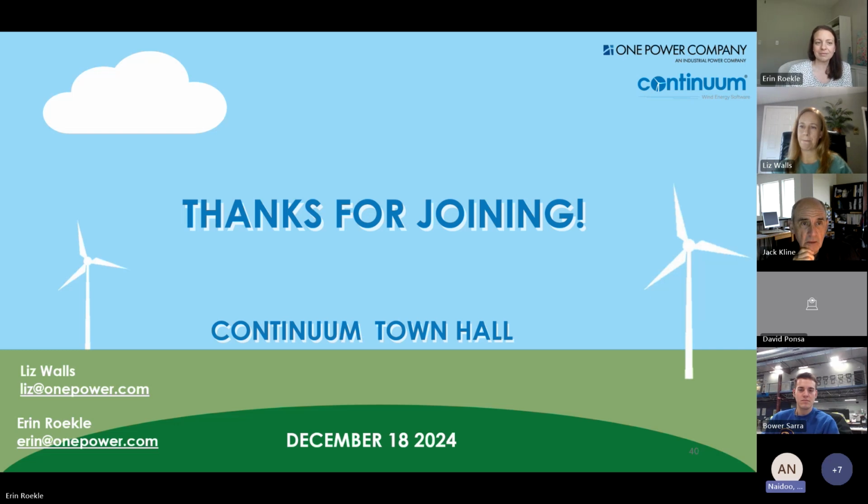The other interesting thing I was thinking with modeling a hybrid plant is if I were to raise the height of the solar panel, say to 10 meters high, within Continuum I'd make the displacement value, say 10 or 11 meters, because then you could have your agrivoltaics underneath. From a city point of view, you're trying to maximize your land use.